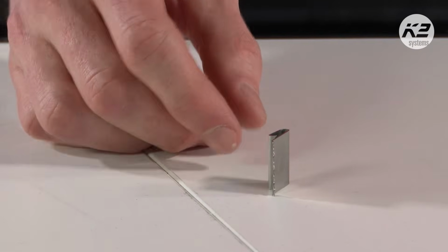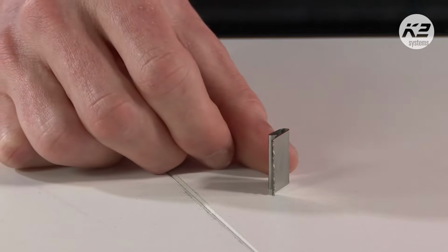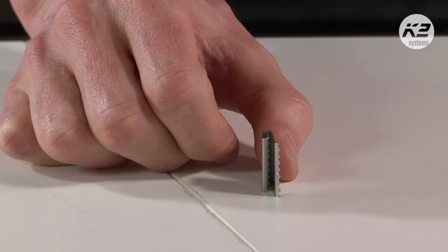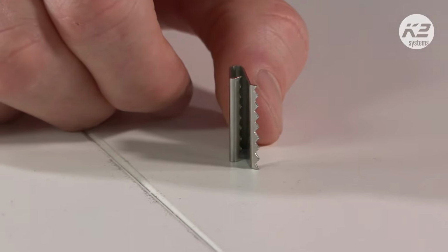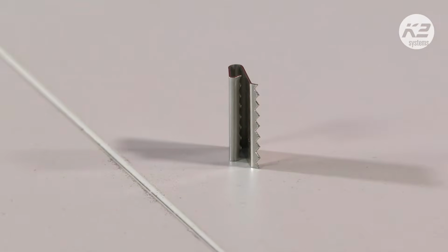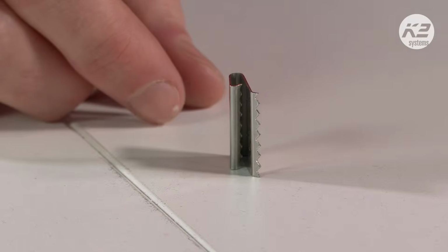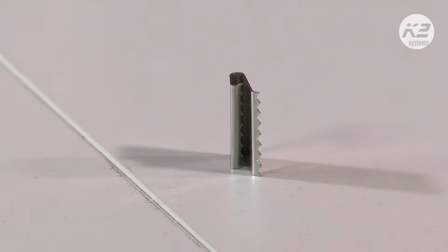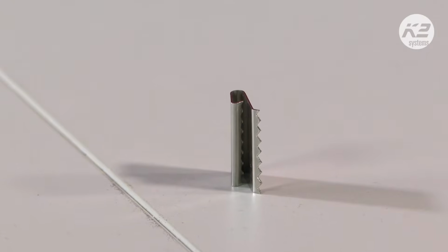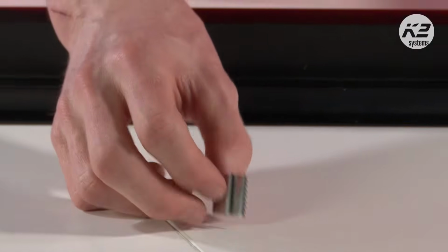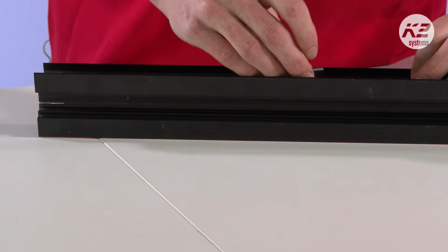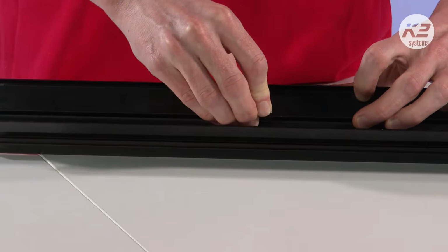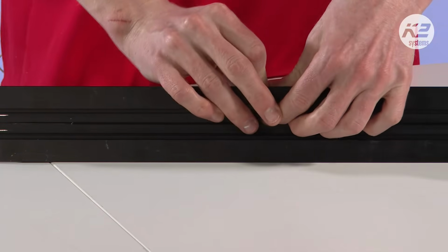It's got little teeth on it, which you can spin around. No, the other way. There you go. You can see these teeth. These bite into the module frame and also through the anodized layer of the rail, more or less. So these are also single-use products. They're designed to ensure that there is electrical connection between the rails, and so we would usually put it just on the frame of the panel here.